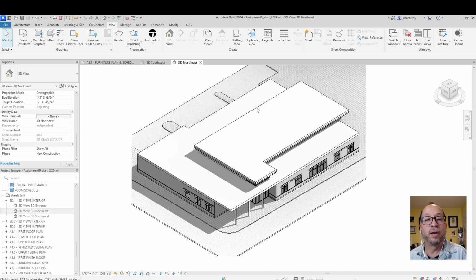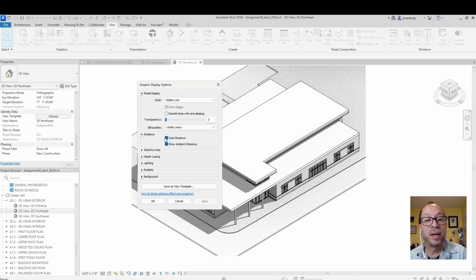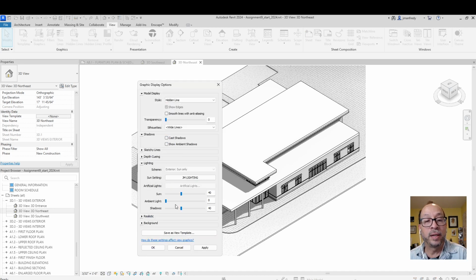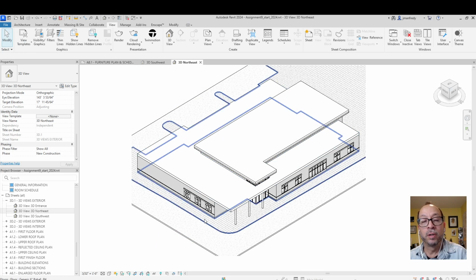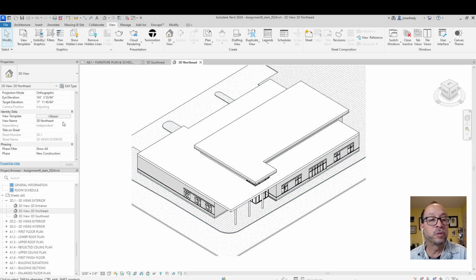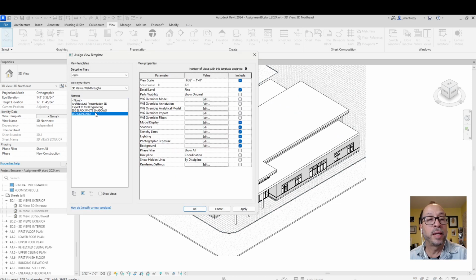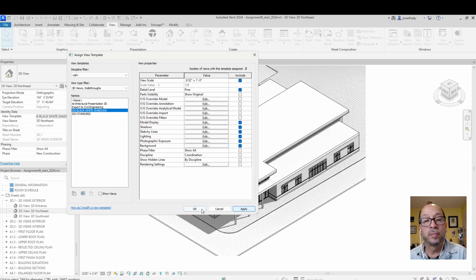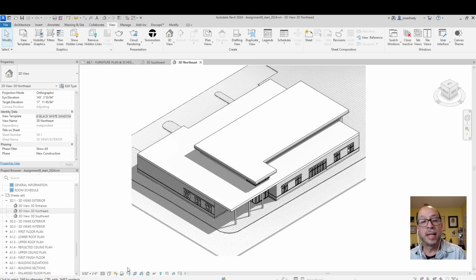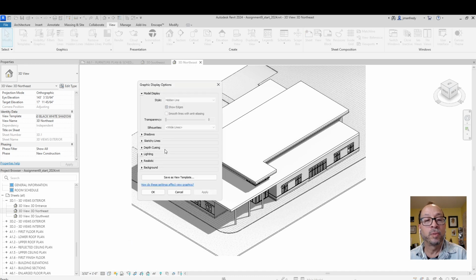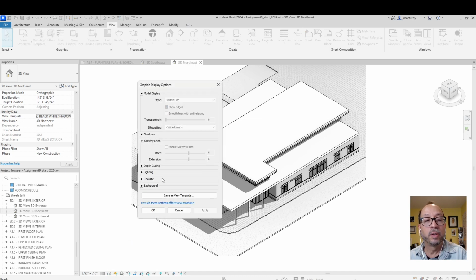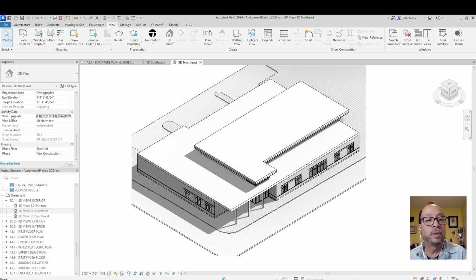And if I want to avoid somebody coming into my file, or maybe yourself by accident, making some changes by mistake and forgetting what the settings were originally, you can simply put the template on here. And the template has all the recordings of all the settings. It goes back to normal. Now you cannot change anything here because these have been recorded into the template. All these commands are disabled. They're not here anymore. They're inside of here, the view template, that controls what this looks like.